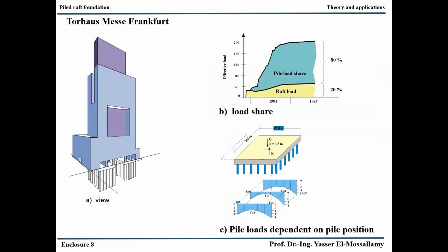Therefore, they said, okay, we will apply the idea of piled raft foundation, applying very simple calculation methodologies at this time. Therefore, they have done a lot of measurements, and this was actually a very nice case for the observational method according to the Eurocode. We use good engineering judgment in the design stage. We put a lot of measurements, and from these measurements, we learn what is actually the real performance of the building, and then we can improve our design for the next project and so on.